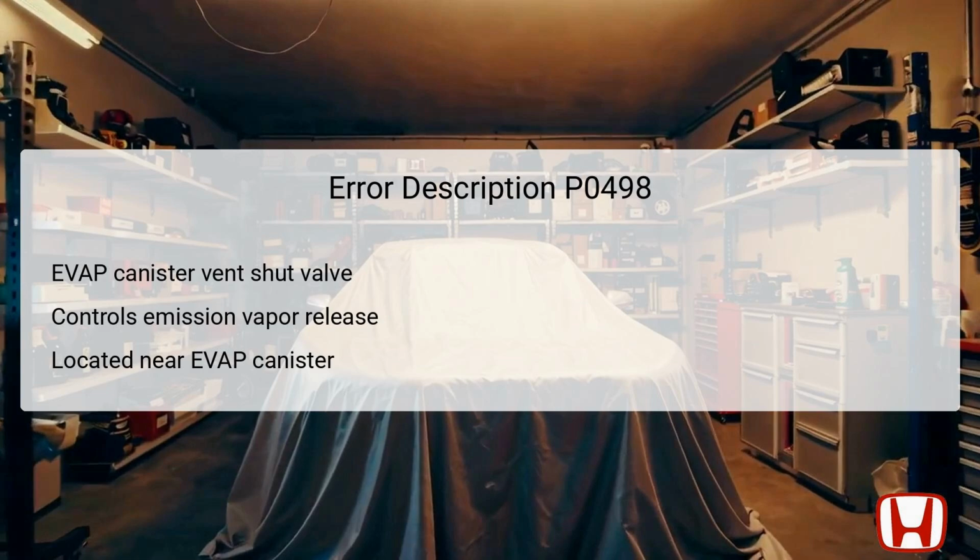Located near the rear of the vehicle, this component connects directly to the PCM, which monitors its operational status. When the PCM outputs a signal indicating the valve should be on, it expects a corresponding response, which would confirm the valve is functioning correctly. If the valve does not send back the intended signal, this low voltage situation triggers the error code.